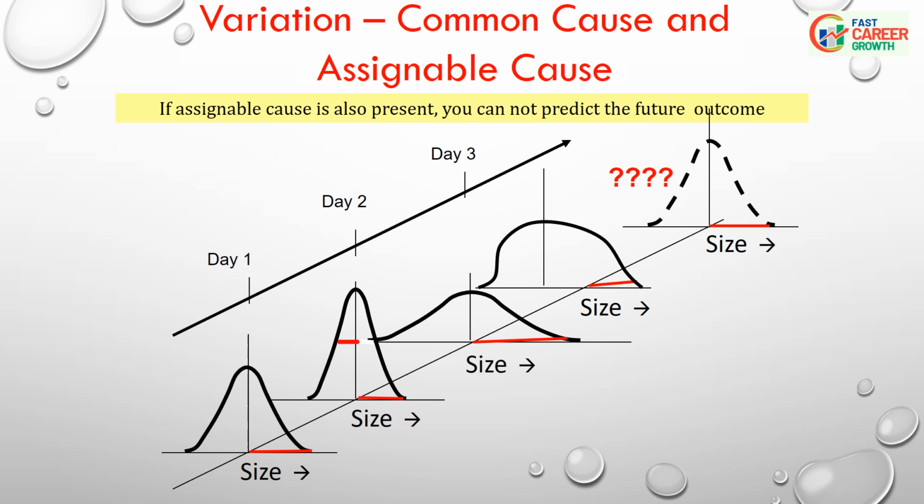Special causes, often called assignable causes, refer to any factors causing variation that affect only some of the process output. They are often intermittent and unpredictable. Special causes are signaled by one or more points beyond the control limits or non-random patterns of points within the control limits. Unless all the special causes of variation are identified and acted upon, they may continue to affect the process output in unpredictable ways.